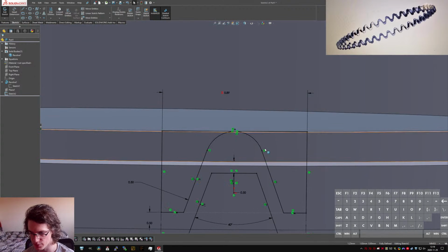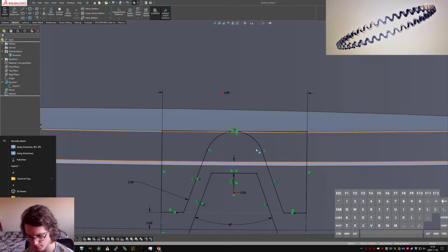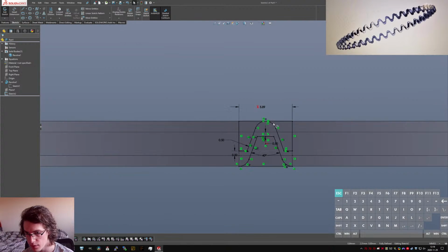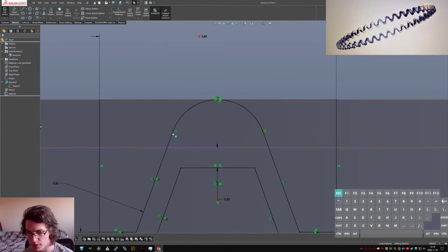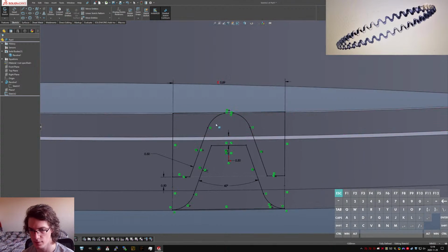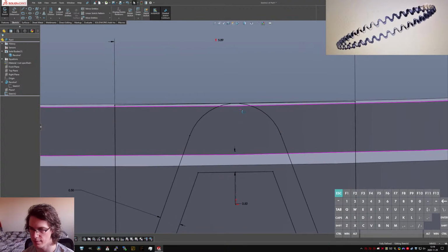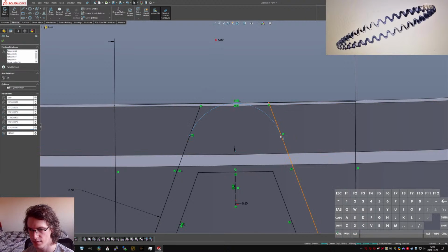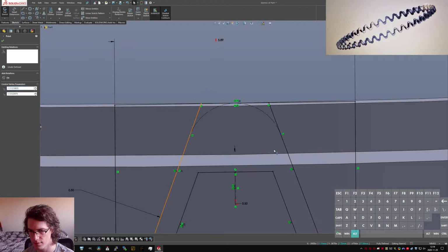This will always extrude with these points. Those edges will come back in that plane. If I do a full round, they'll come down because the faces will get a little bit wider apart. I don't really feel like showing that, but I don't know. Imagine it. Just have a good imagination and imagine it in your head. Make those coincident again.